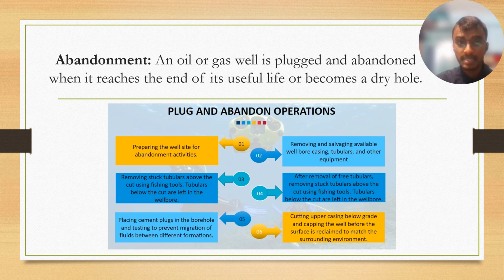Then, placing cement plugs in the borehole and testing to prevent migration of fluid between different formations. Plugging is subject to federal and state regulations. Regulations may vary from state to state.